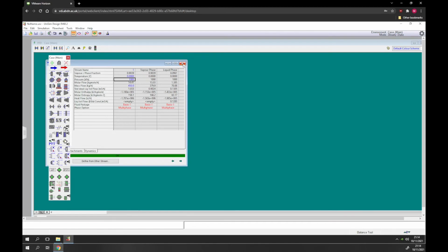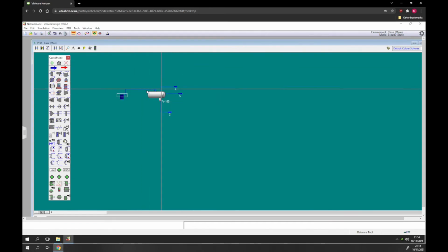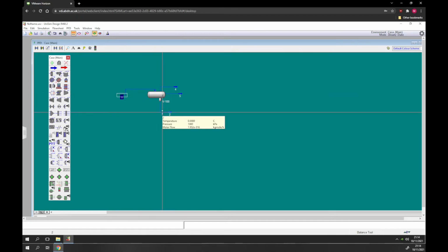And now what you'll notice with this 3-phase separator is we have 14.41 kilogram moles coming in. Now we have 13 kilomoles of gas coming out the top, and 1.385 kilomoles coming out through this liquid stream here. But at the bottom you see nothing coming out, and this is because water would normally come out this place, and we haven't got any water in here.